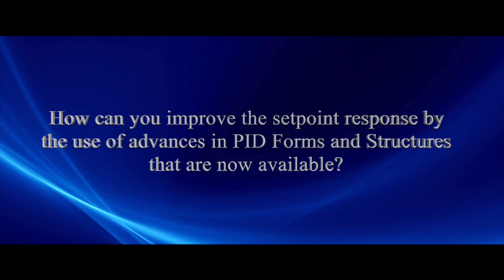So this opens up a possibility for you. The standard structure often used today with the ISA standard form is proportional and integral action on error, but derivative action on PV. So if there's a set point change, you are not going to get the kick from the derivative mode. That's already kind of a default. In biological processes, they're so worried about overshoot that they will choose integral on error, with proportional and derivative on PV, so there's no step as well as no kick from a set point change.